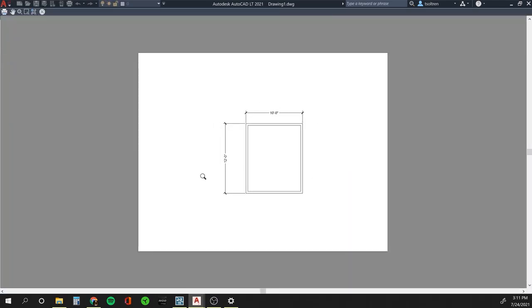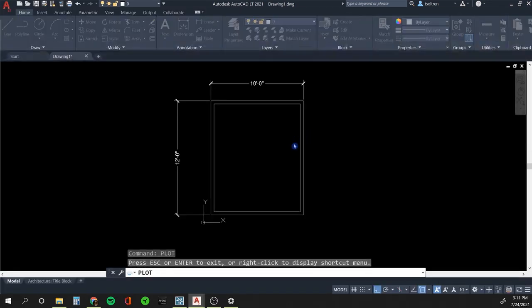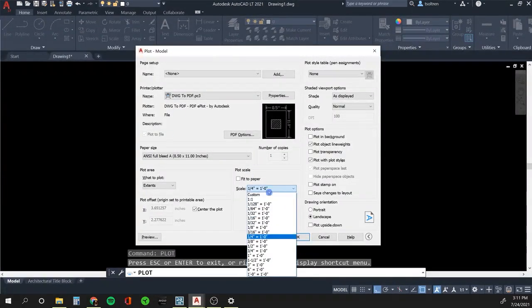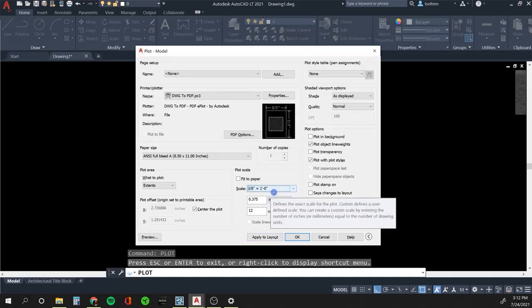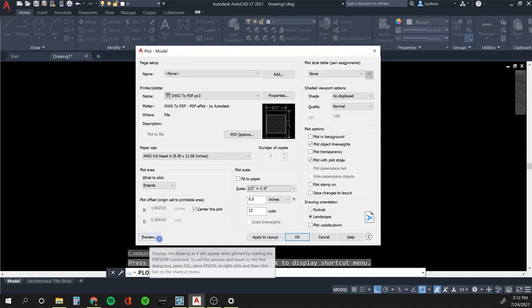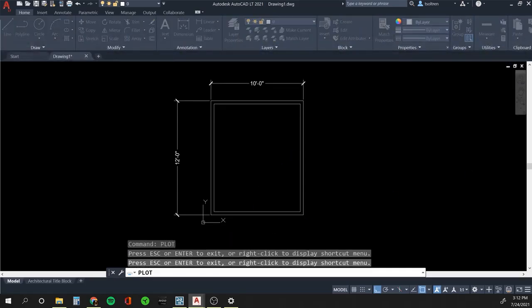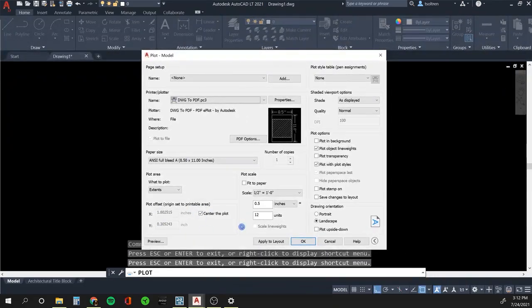So we have our drawing printed out to scale, so you can actually plot this on an 8.5 sheet of paper and use a 1/4 inch ruler, and it would be 12 by 10. That would be correct. And we can pick whatever other scale dimensions you want. So you can go to, as long as it fits in the paper, or it doesn't even have to fit in the paper, it'll just be cut off the screen, but you can see what would better work for your situation.